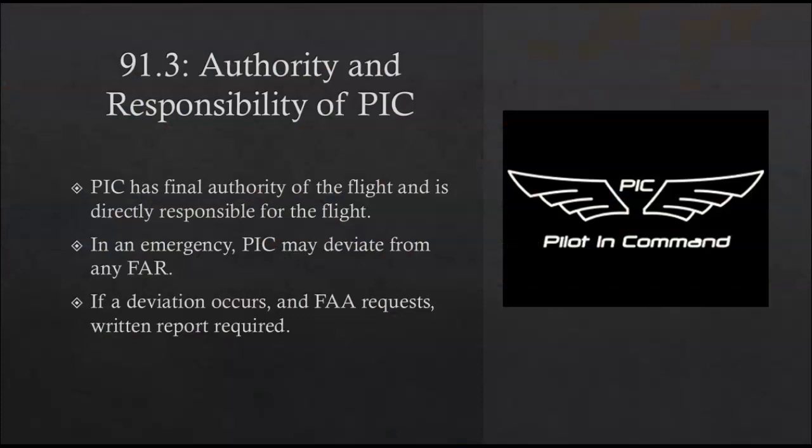FAR Part 91.3 is about your authority and responsibility as the pilot in command. The pilot in command has final authority over a flight and is directly responsible for the flight. In an emergency, the PIC may deviate from any regulation, and if a deviation occurs, the FAA may request a written report. But a written report is not required in all situations, only if the FAA requests a written report.